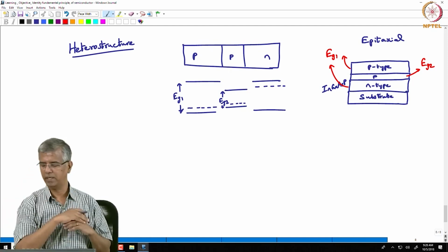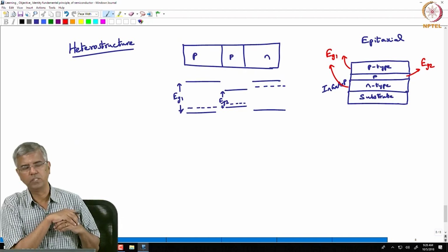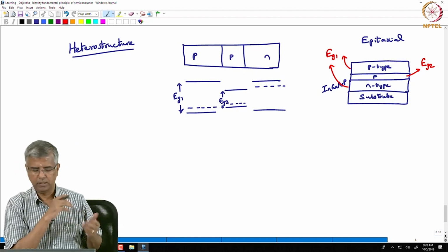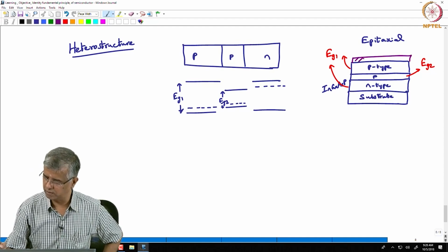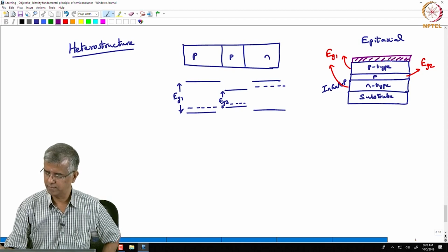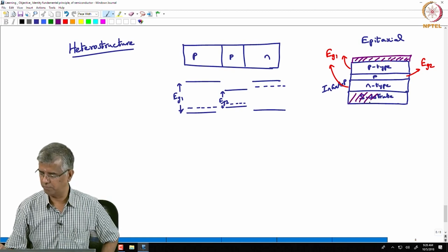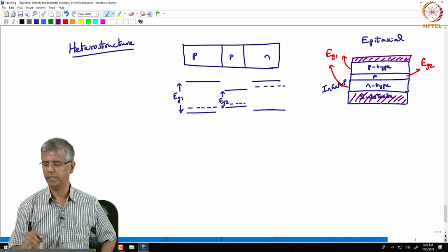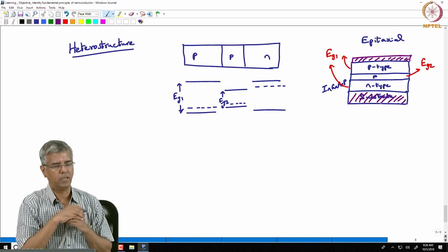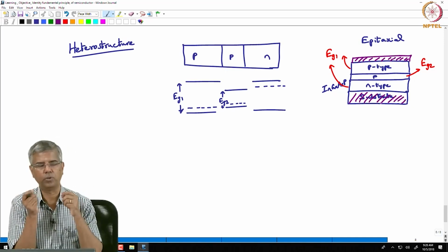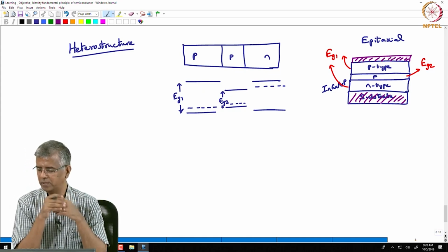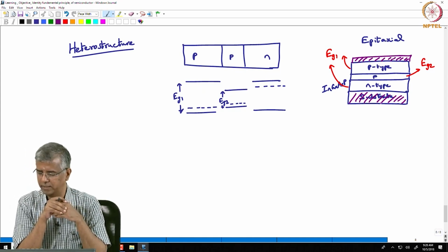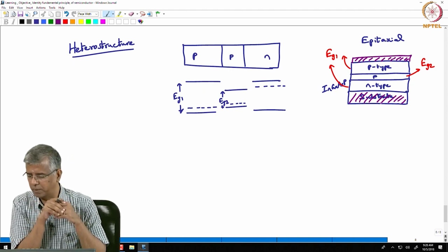So, but your overall structure is going to be like this. Basically all these layers are sandwiched between two metallic contacts. So you deposit a contact over here, and this substrate itself, you may have a contact over here, and then you have a possibility of connecting that to an external bias source, and you have your light emitting structure or your detector also, depending on what sort of bias you put.